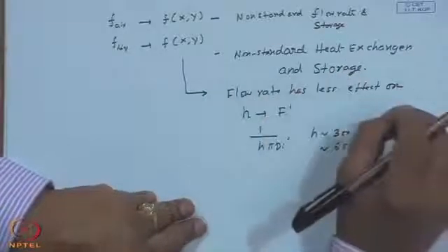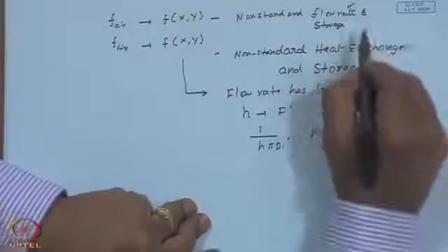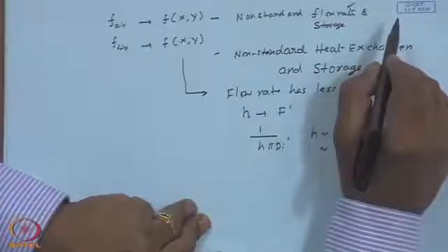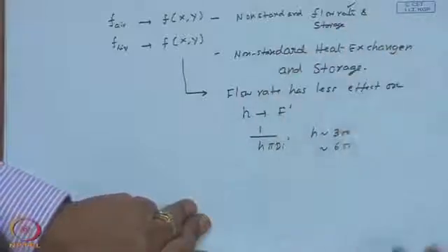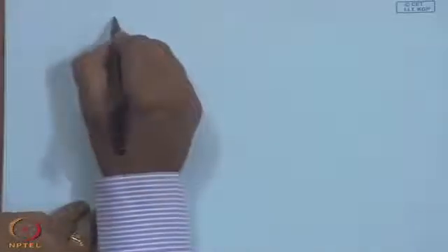whereas for air systems flow rate is an important thing, and the correlation is standard for 10 liters per second per meter square of the collector area. For other flow rates, we need to have the correction. So, that is the philosophy in providing a correction for the flow rate for air based systems, and such a correction has not become necessary for the liquid based systems, since the convection resistance in the case of liquid based collectors is quite small. So, the general need is also the third one.